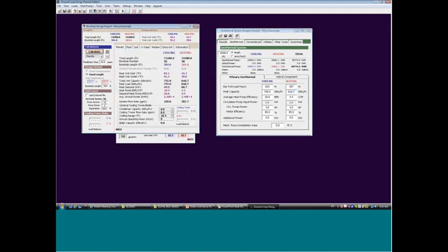What it brings in then is my average calculated performance efficiencies, 20.6 and 4.4. This is really where you want to have an advanced simulation engine because it enables you to predict the average efficiencies as opposed to just using a static worst case scenario analysis that less detailed simulations can only provide. We do have pump circulation power basically. I sized the circulation pump for the system, assuming a very high efficiency design. I think it's like a 3 horsepower system, just as an example. And then in terms of additional power, I'm going to ignore it, leave it blank.